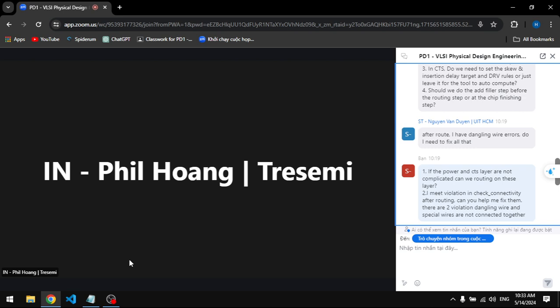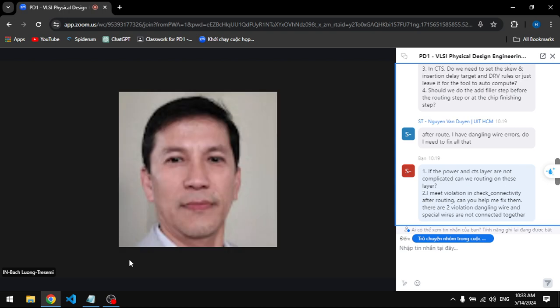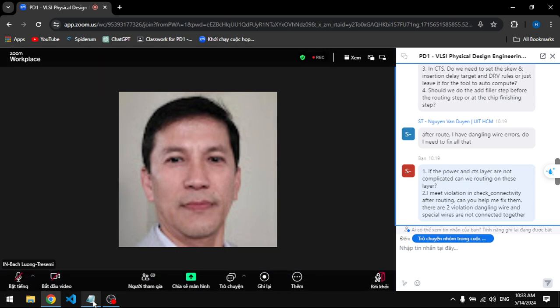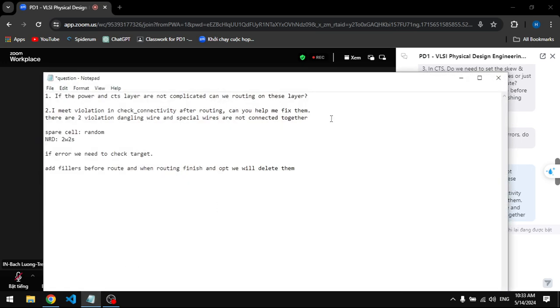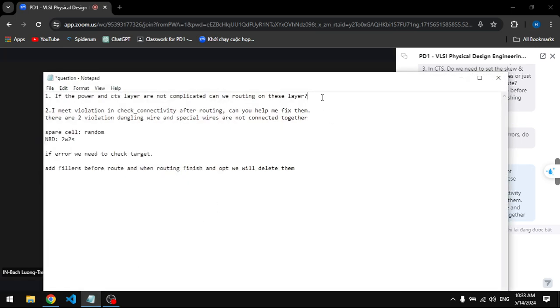For the project, there are scenarios where you can't use upper layers. If you're doing IPs with 10 layers and the top 2 layers are for power routing at the chip level, then they forbid you from using those 2 layers. They'll tell you that. But if they don't say anything, like for this project, you have 9 layers, so open it up for all 9 layers.